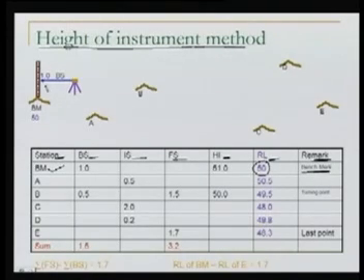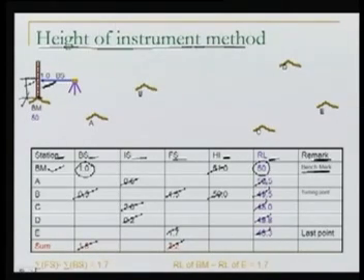The moment we have taken this backsight, and the backsight is 1.0, the meaning is that on this staff the reading is 1.0, so I'm writing this backsight reading here now. So far, don't bother about any of these other columns, okay? All of these are just blank. We are only bothered right now about this empty table, which I have filled only here. So I'm writing this 1.0.